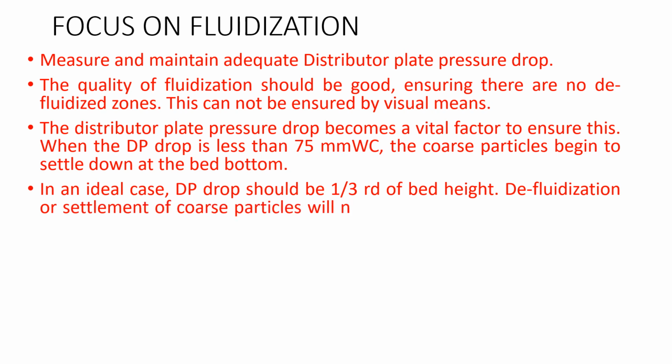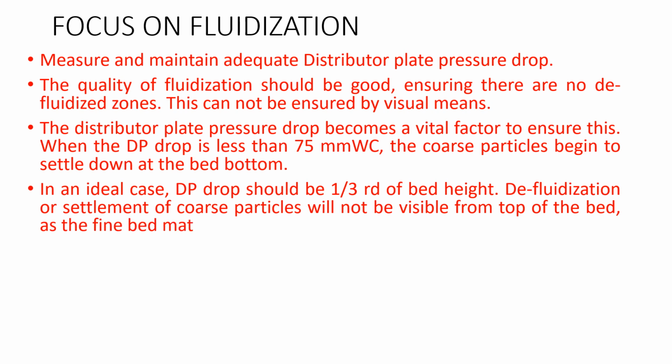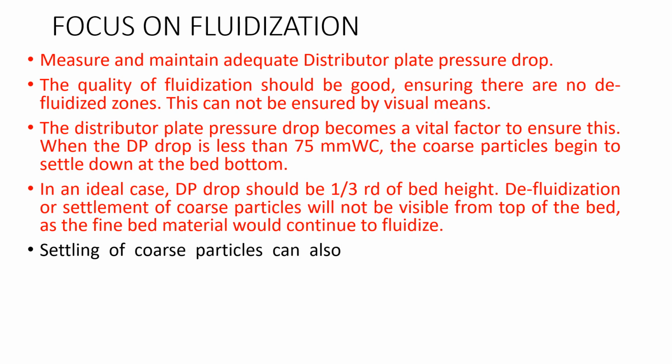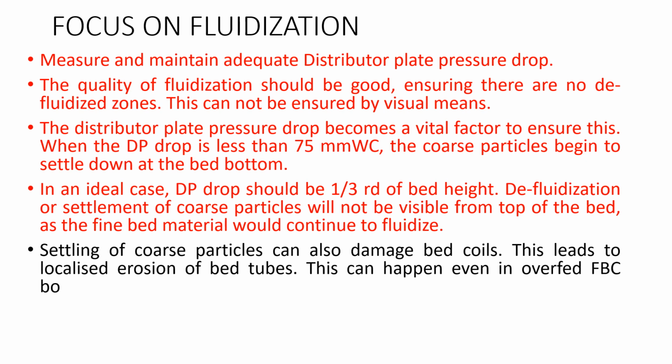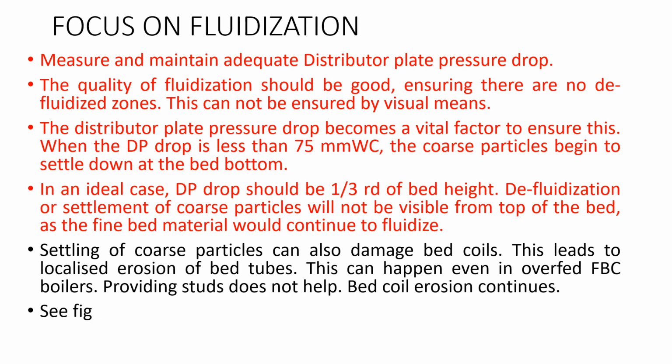Defluidization or settlement of coarse particles will not be visible from the top of the bed, as the fine bed material would continue to fluidize. So settling of coarse particles can also damage bed coils. This leads to localized erosion of bed tubes. This can happen even in overfed AFBC boilers. Providing studs does not help.